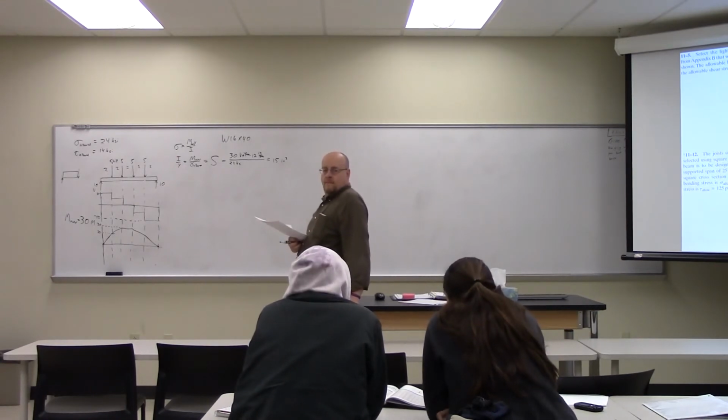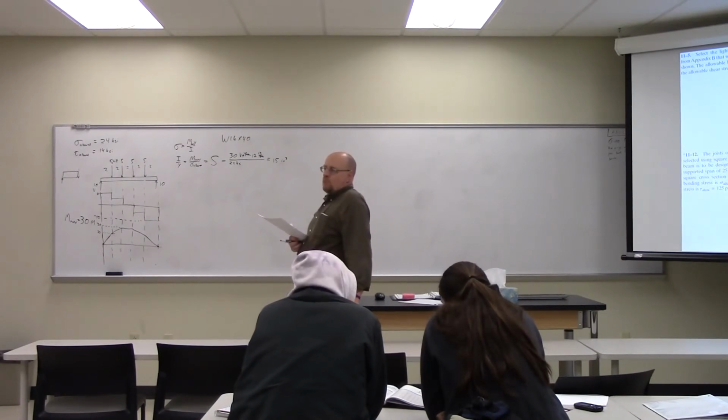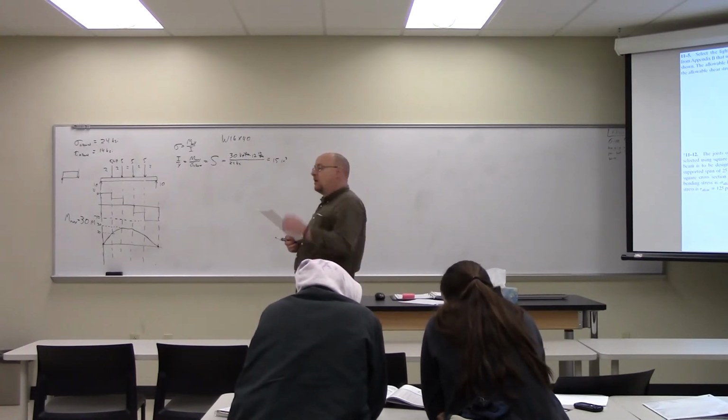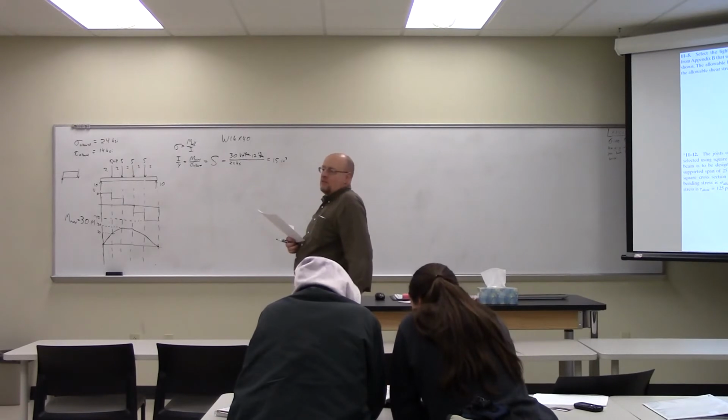The one with the smallest volume, because they don't have the same density. Even easier than that. It's just the last number, the lowest number. Right, the smallest of the second number. The second number is the pounds per foot, weight per unit length, and so you want that number to be small. So that one is 40 pounds per foot? Right, and 16 inches high.